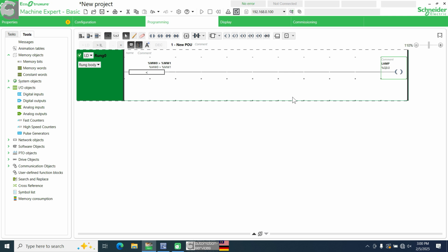Why, if MW0 is 16-bit and MW1 is 16-bit, can you not use MW2? You can use it. What I am trying to say is, MW means 16-bit, MD means 32-bit.